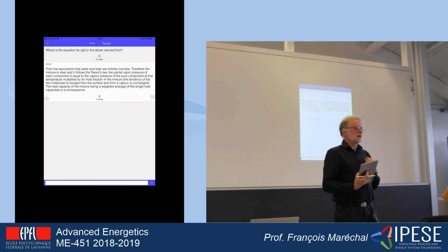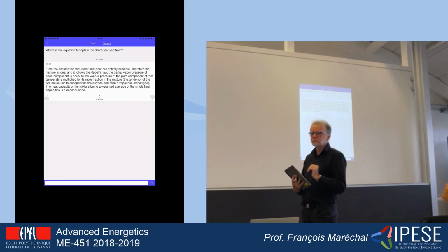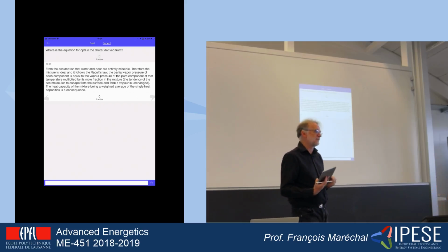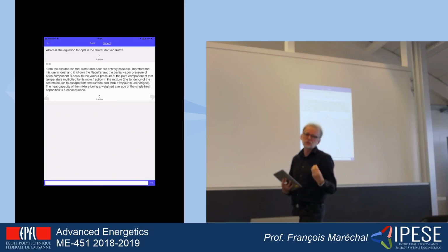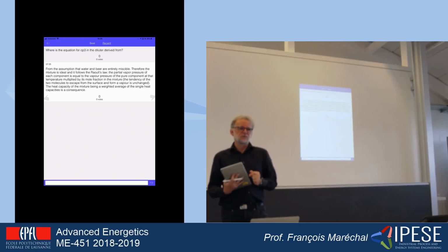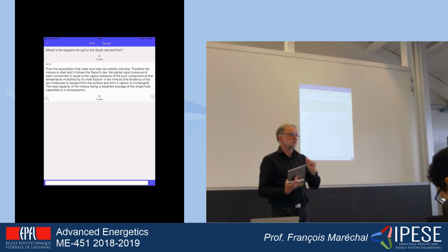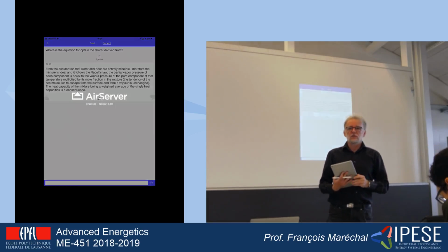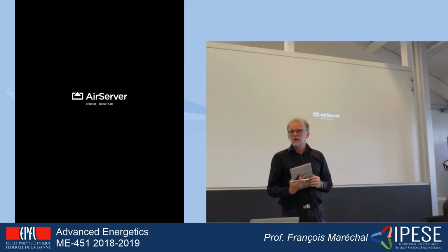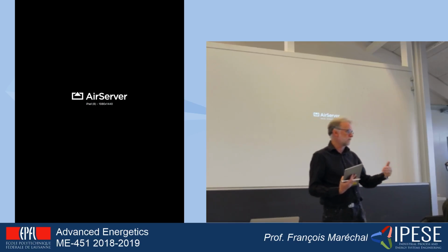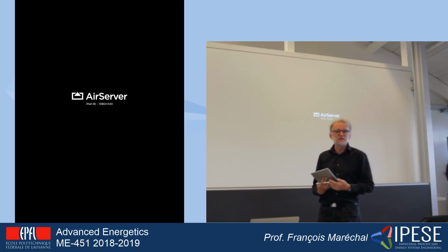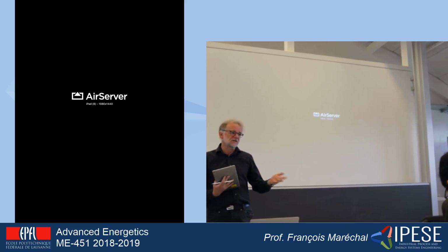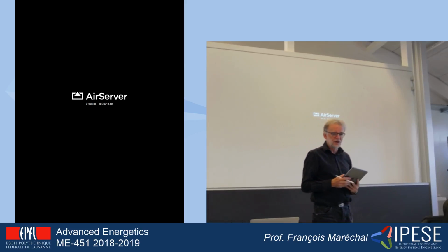CP. As soon as you know the CP of water, and as soon as you know that the flow of beer is not going to be affected, so the flow of alcohol is not going to be affected, by using the temperatures that you receive, you will be able to identify the value of the CP of the beer. And therefore, as soon as you know the CP of the alcohol compared to the CP of water, you can apply the same principle everywhere by summing up the flow of alcohol and the flow of water. This is valid, of course, if you remain in the liquid phase. As soon as one of the two compounds goes in the gas phase, the calculations become a little bit more complicated.